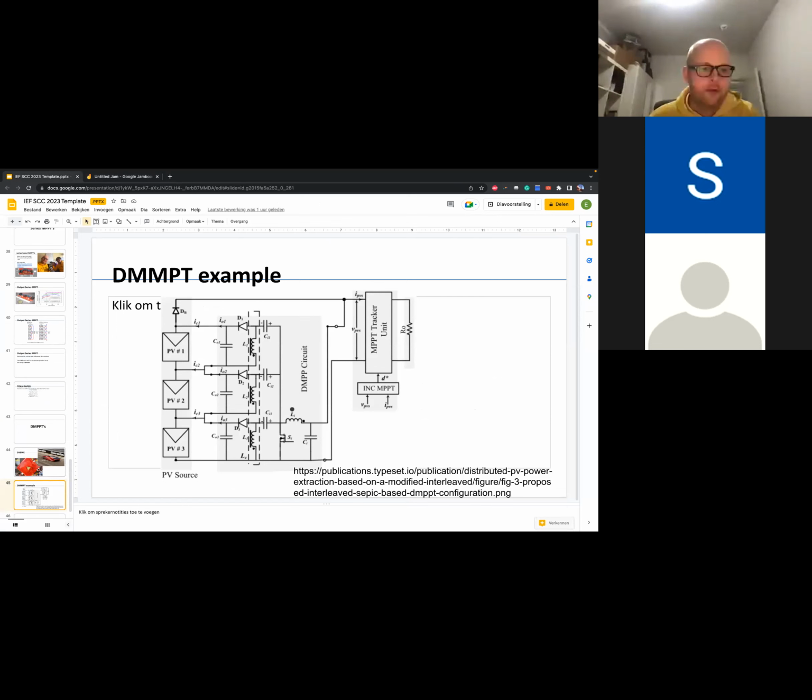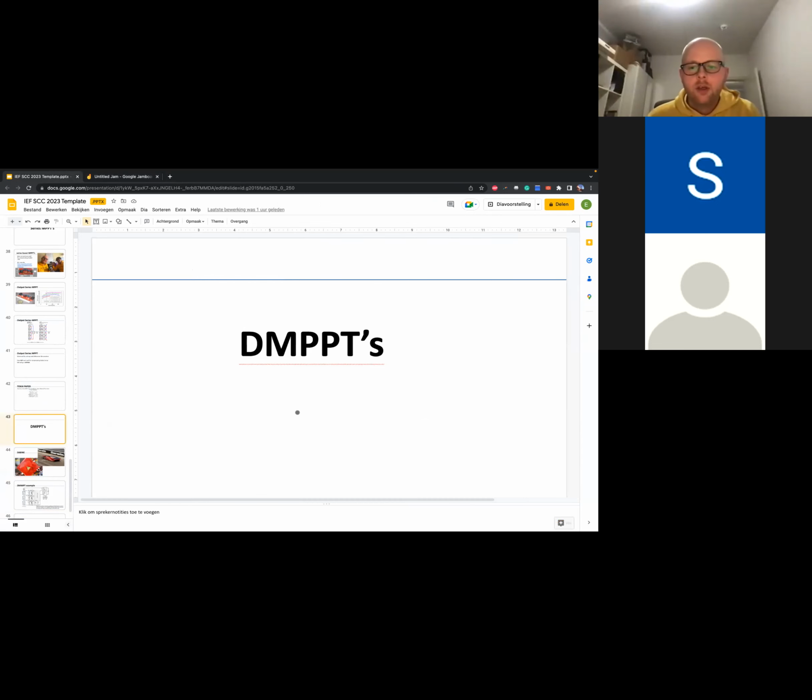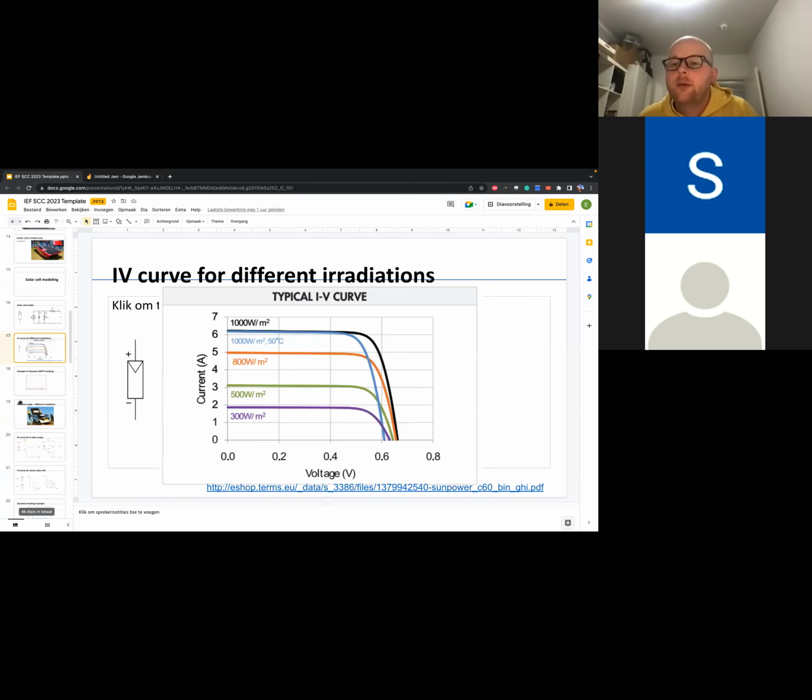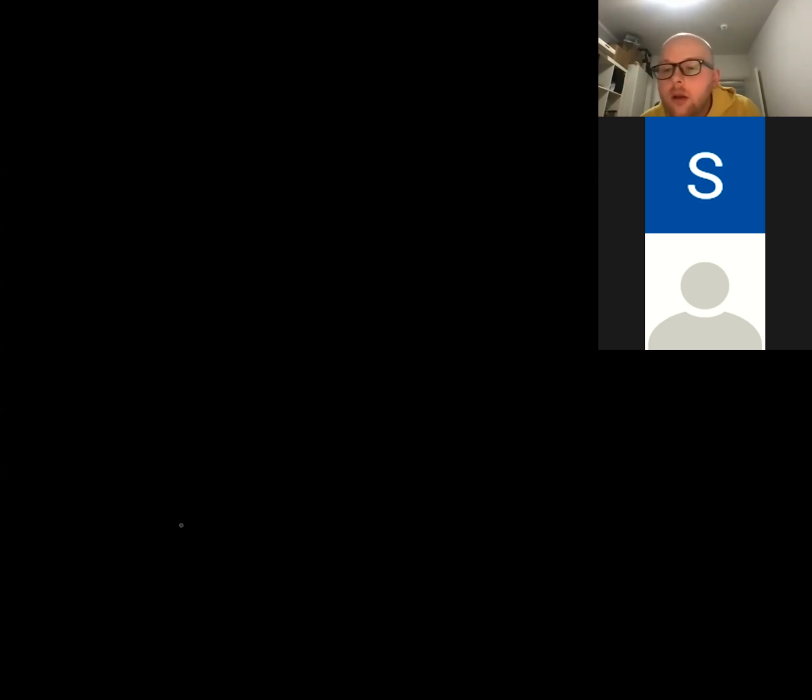I want to go back to the MPPT graph for a bit. So here, you see that the maximum power point voltages are the same. They're not really dependent on irradiance. So capacitive balancers could work, but they are dependent on temperature, for example, and also on how many cells you put in series. So if some section of the array is warmer than the other one, the capacitive balancer already doesn't work as well.